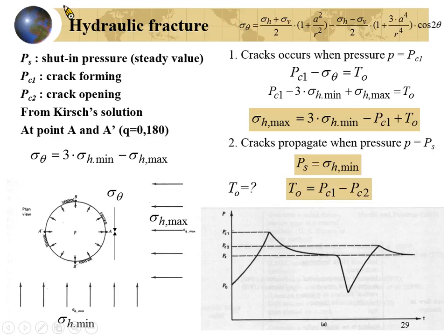It's so easy. Because the fracture will form at the lowest resistance. The lowest resistance in the horizontal cross-section will be 14 MPa.